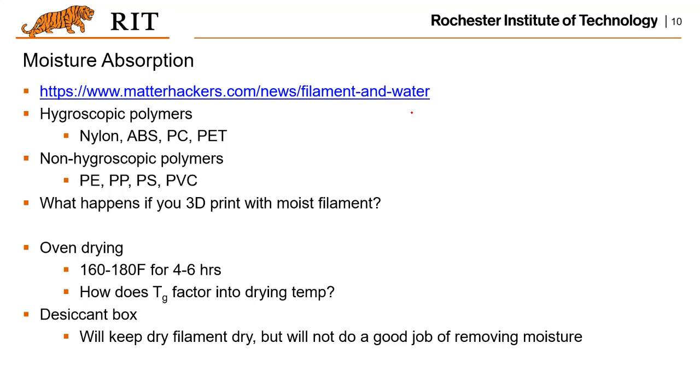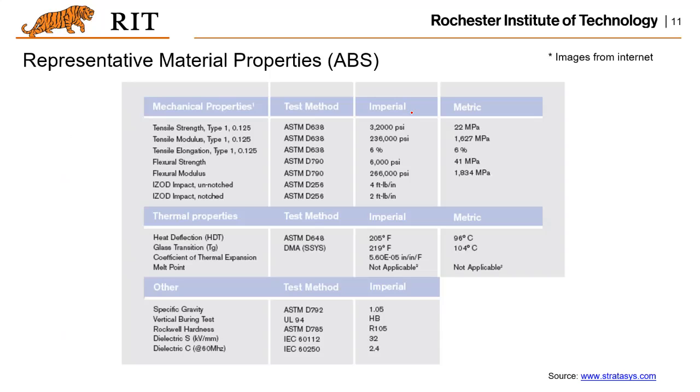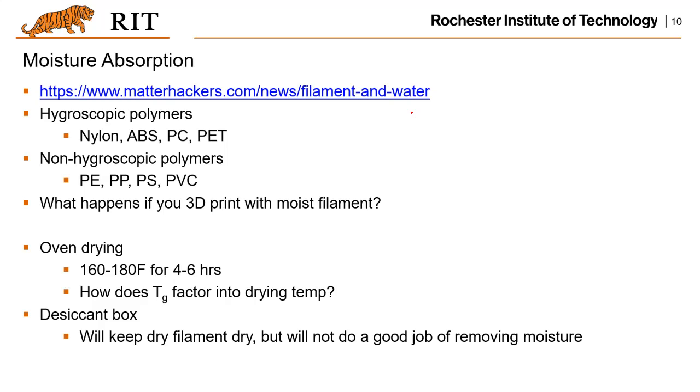Just imagine if you have moisture in your filament: when the filament is heated up, the moisture is boiled and it could generate bubbles. That will leave some empty void space in your printed part, which is undesirable. That's why you don't want your filament to be exposed to the air for a long time, and that's the reason.